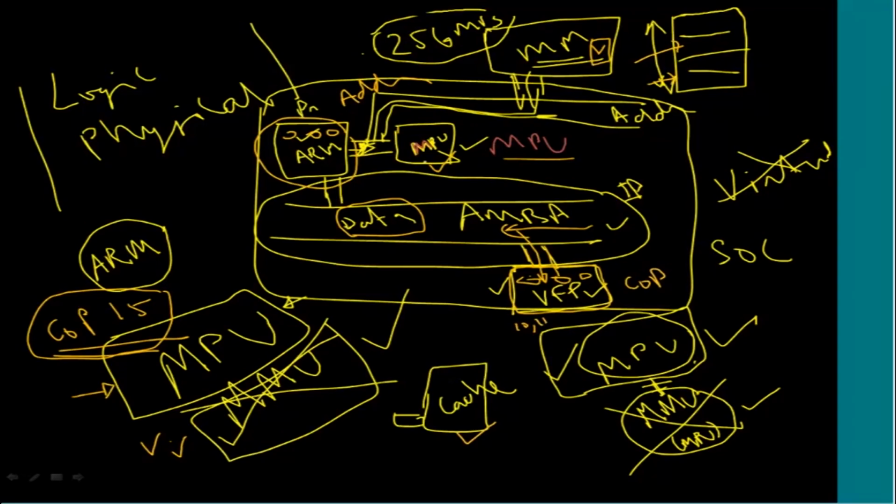If it has to perform the job of protecting the memory accesses, it should know what the ARM processor is accessing. As I mentioned earlier, the address generation is with the ARM processor. Nobody is going to control that because our instructions which are getting executed in the ARM processor only control how the addresses are generated by the processor.